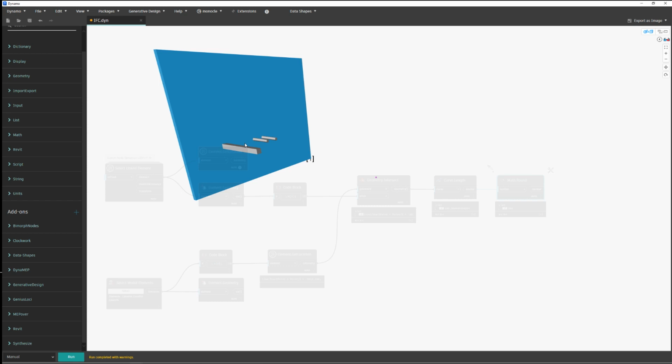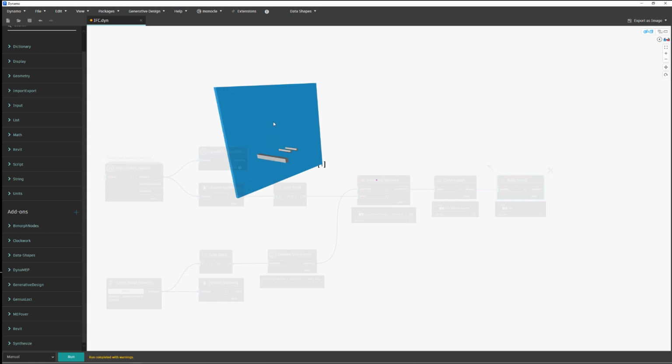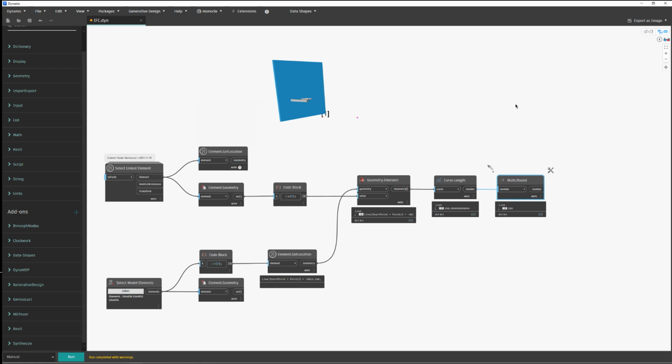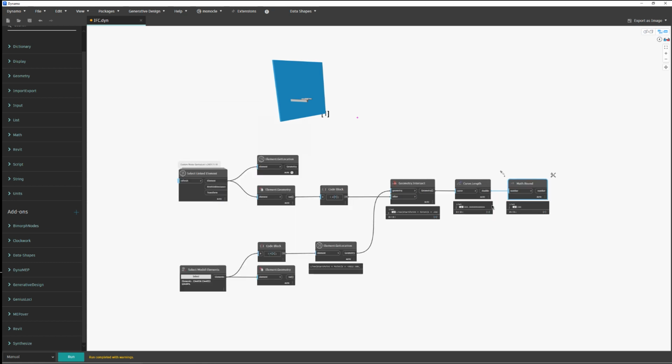So you can either create a bounding box or any other element, and then you will just need to read what dimensions you have for that bounding box for the height and the width. You can also try to find the thickness of the wall if you want to know the length of that bounding box, but sometimes you will have incorrect results. I would say in most cases you will have incorrect results, but you can try and you can compare it to this case over here.